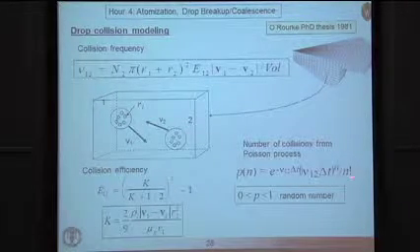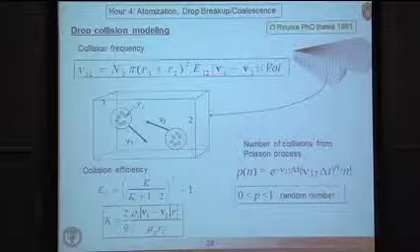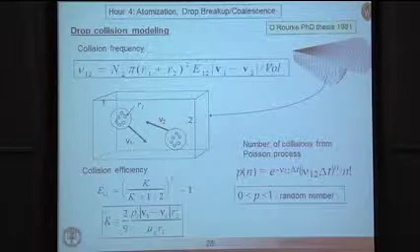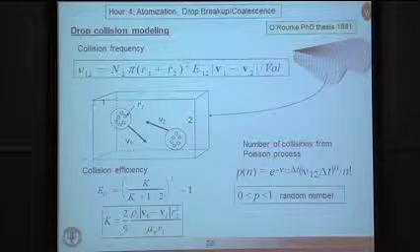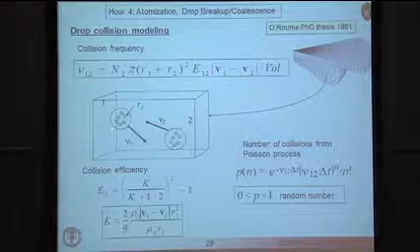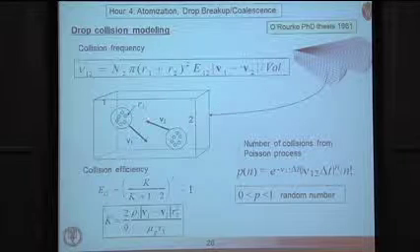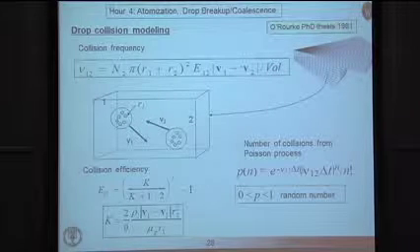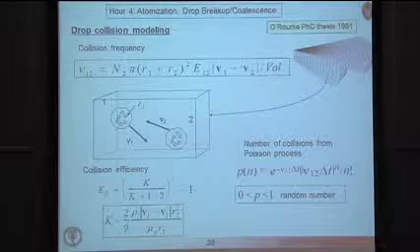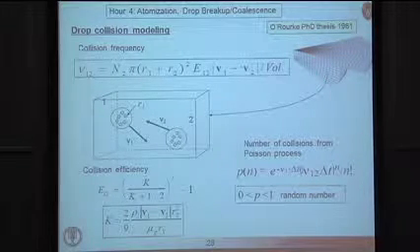So that's what my N was over here in this Poisson thing here. I assume the left-hand side a random number. I know the collision frequency, and I know the time interval between when the last collision occurred and now. That would be my numerical time step. And I can now calculate n. So that tells me how many of these droplets I'm going to allow to collide. And then I make an adjustment to the number in this that I leave untouched. And the rest of them, I go through this exercise of determining what kind of collision outcome to expect. So what I guess what I'm asking is, rather than looking between, I understand this is between two sets of two different parcels, the droplets between two parcels.